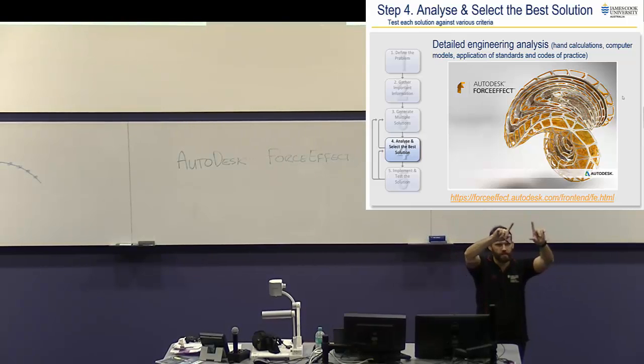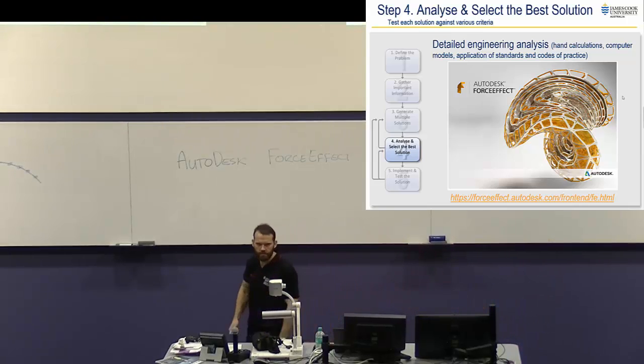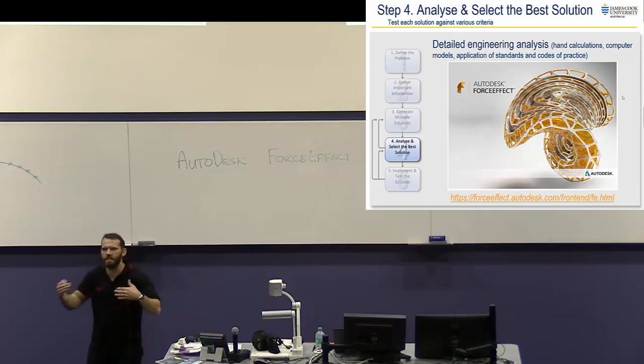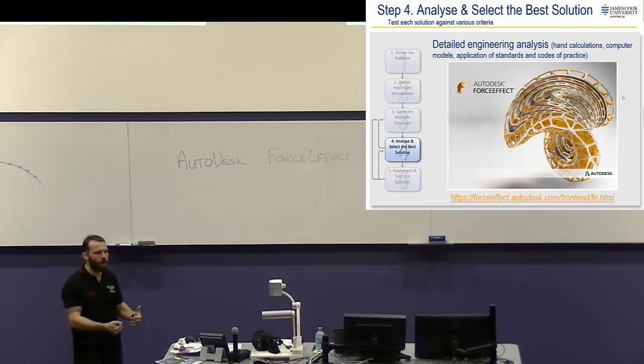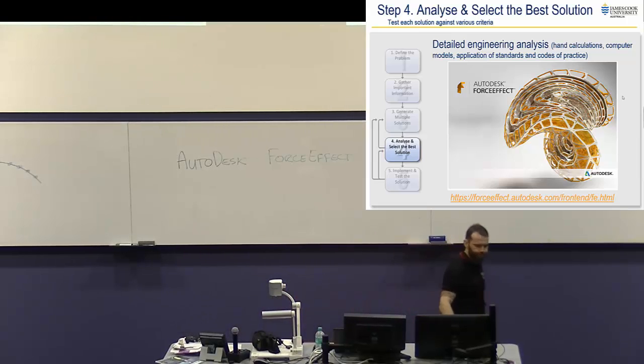So there's ways, obviously a triangle will always be set. Once you set 3 dimensions, that triangle won't move. So if you're trying to do rectangular stuff, maybe throw some triangles in there with some dimensions and that'll fix it in space so it doesn't get all, you know, crazy and silly geometry. And then you can just remove it or just use construction geometry. So you just have to think carefully about how am I going to get the geometry right using that type of technique, and then you'll have your bridge.